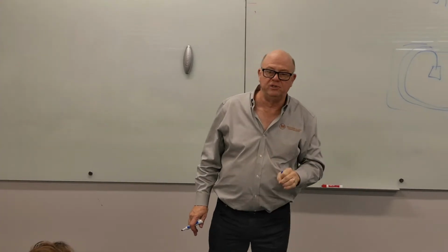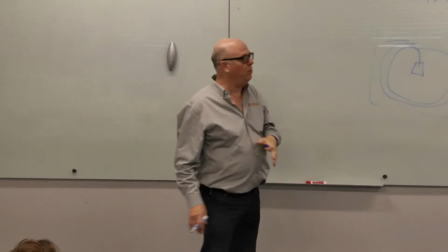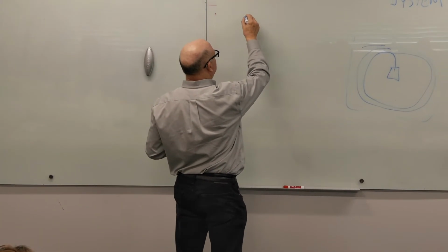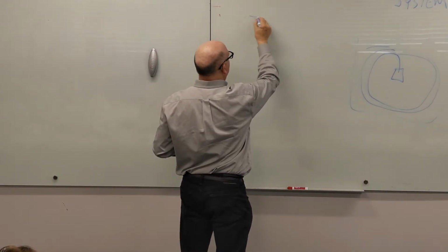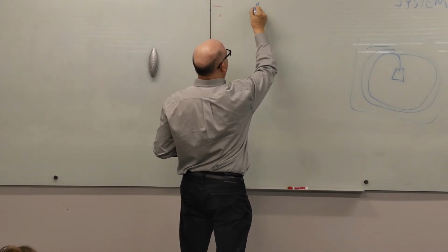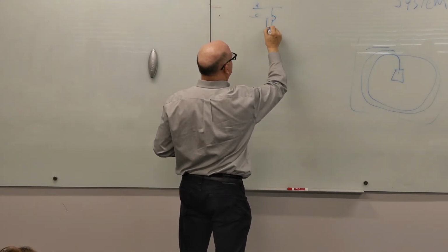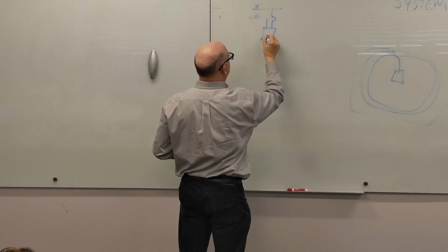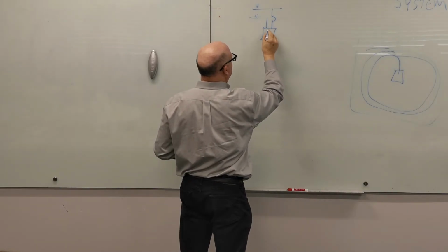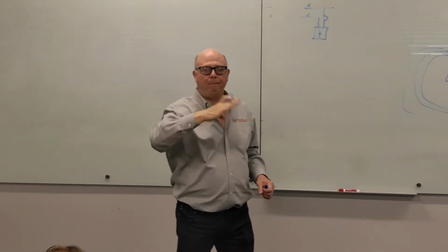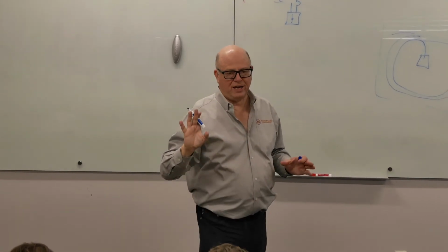back before 1973, the way that we would do this is we would use a mixing box usually. So you've got a cold duct, and you've got a hot duct, and you would come off here, and you would come off here, and you'd go to a mixing box that would have one damper and one actuator.